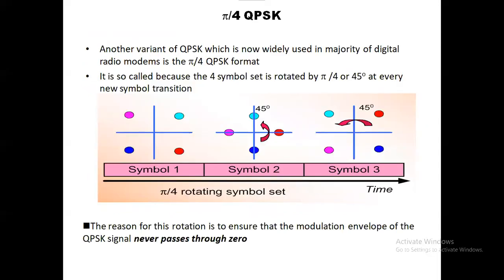So there is another variant of QPSK which is pi by 4 QPSK. The pi by 4 QPSK, in fact, has transitions of plus minus 45 degree. You may be surprised at how to perform this, because this cannot be done by a single constellation. It has a dual constellation. One has an initial offset of 0 and the other has its initial offset set to a different point.